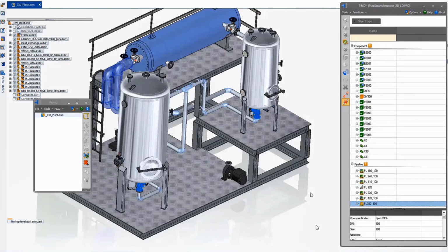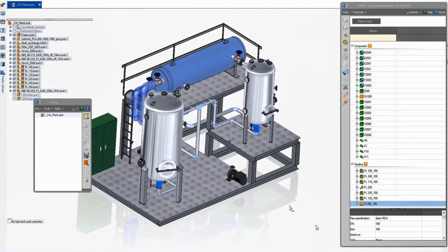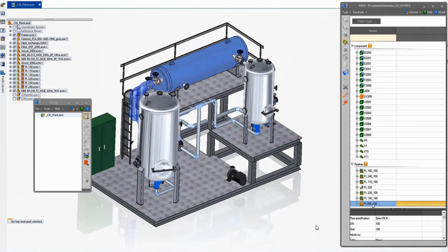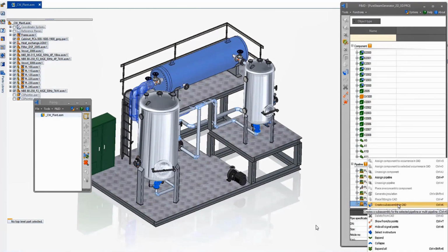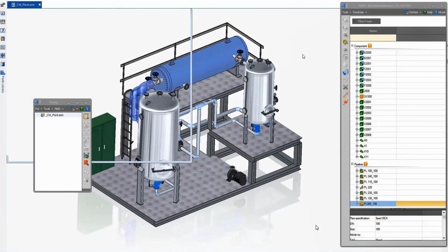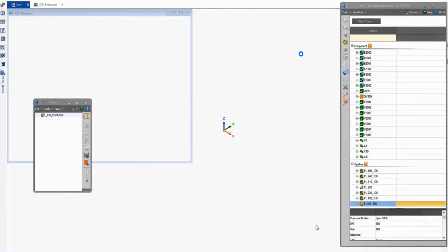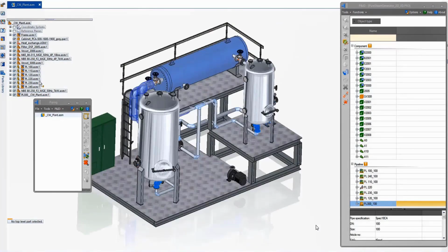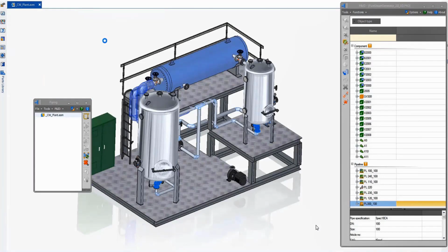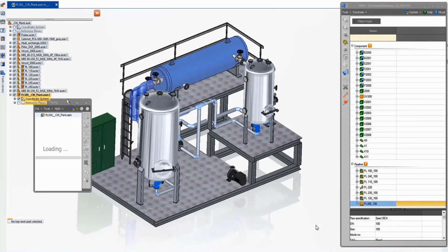Once the path location is understood, it's time to create the path. First, a subassembly is created to store the piping information, and then we'll go into that new subassembly. Then we can use the routing tools to enable us to automatically create a route from the 2 points highlighted earlier.